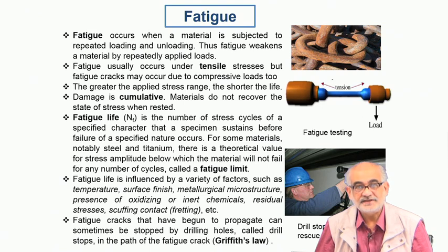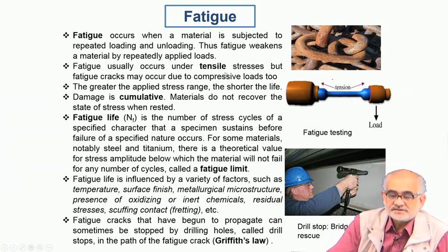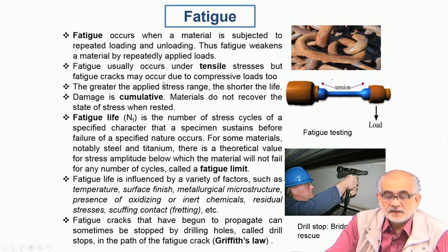So one has to take care of not only the tensile or compressive component of loading, but also check whether we expect fatigue or a cyclic loading condition.